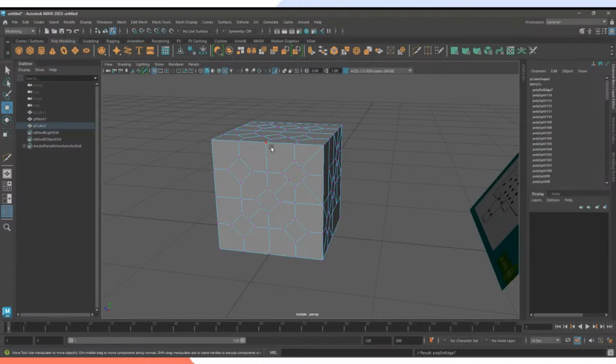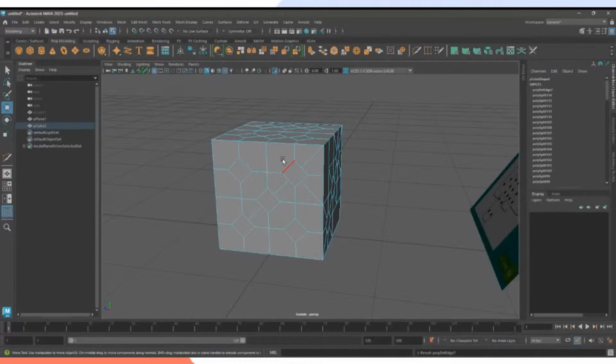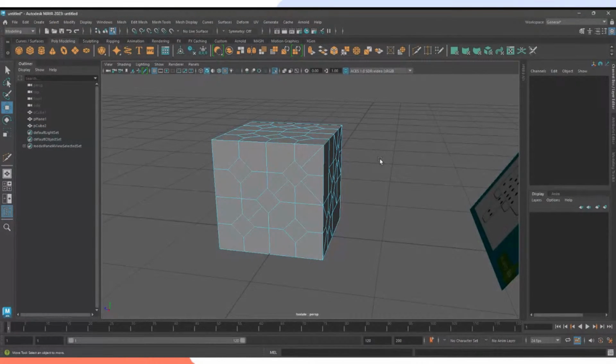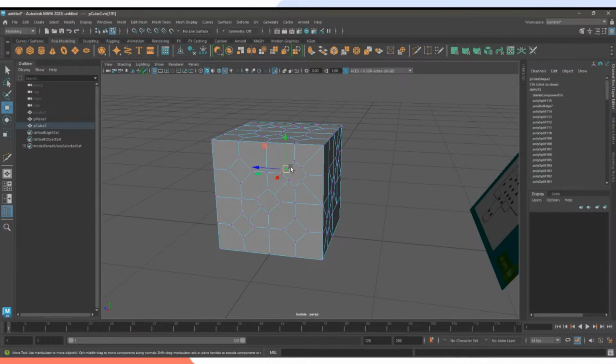This removes both the edge and the vertex over here. Because, for example, if you make that same mistake and you only select the edge and then just press backspace, the vertex is still there. And sometimes you don't want that vertex to be there. So if you also delete it, it might work.